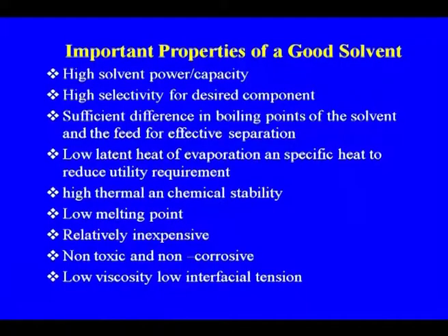High solvent power capacity, high selectivity for the component which has to be removed, sufficient difference in the boiling points of the solvent and the feed for effective separation, low latent heat of evaporation, high thermal and chemical stability, because stability is also very important as in some cases we are using high temperature, low melting point, relatively inexpensive, non-toxic, non-corrosive, which is another requirement of the process, low viscosity, and low interfacial tension.